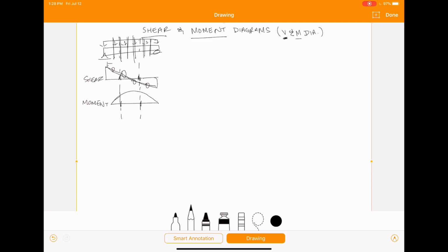If this beam was 10 feet long and you needed to know the shear at 1 foot lengths, using the knowledge from the previous video, you would have to cut this beam 10 different times. However, if we develop a shear and moment diagram, then we can just pull those values off that diagram, and it takes about 1/10 of the time.